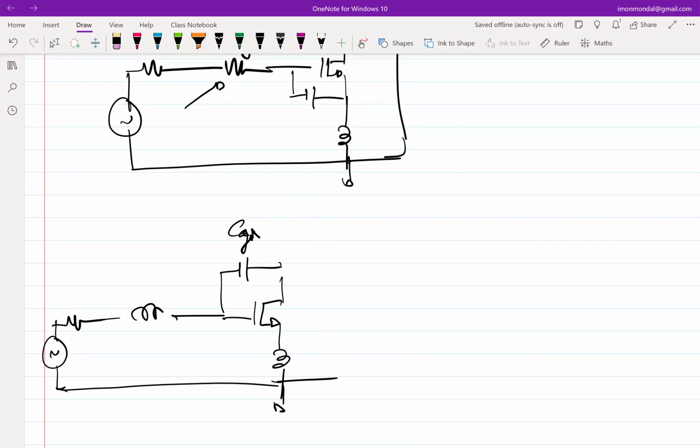By the way, the other thing that I have neglected is at the output, we have only talked about short circuit currents. When the output, we are going to have a load, right? And typically for very good LNAs, you cannot have a very explicit resistive load. Generally, what is done, you put another resonant network, or you simply put an inductor, right? And the inductor gives you the load. But if you are not getting sufficient impedance because of inductor only, you resonate it out.